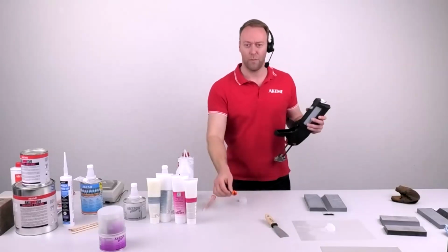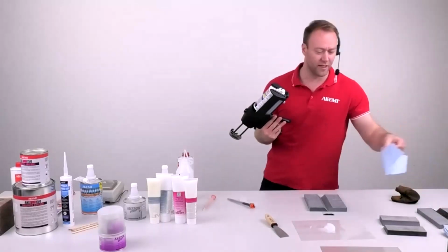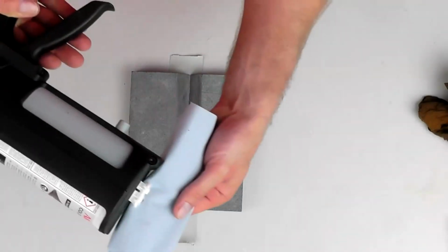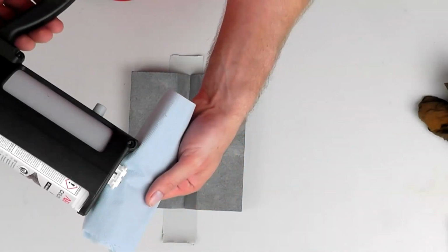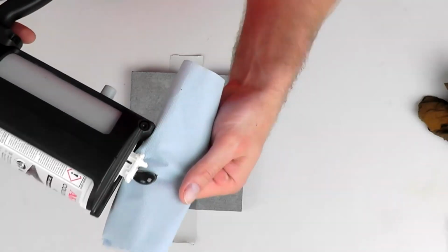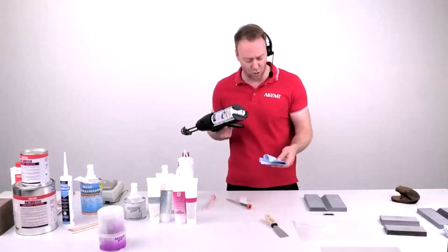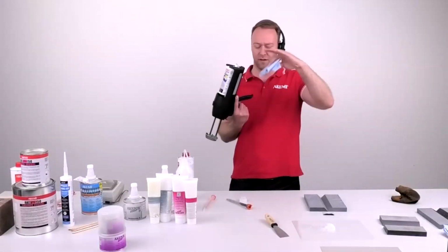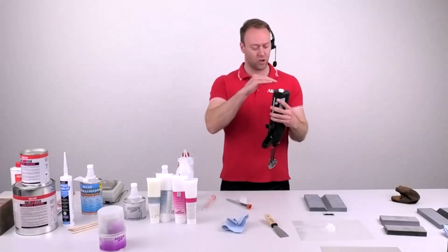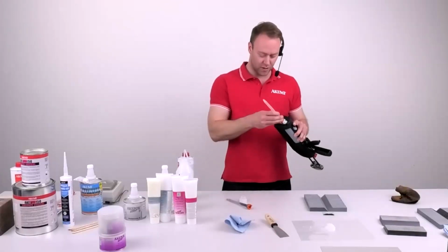Also here, with the mixing ratio you cannot make any mistakes, so you have to be sure that the mixing ratio comes out in a proper way. When you use a cartridge for the first time, press as long as both components come out of the chambers, because maybe during transport there will be a different filling status. So press them out so you're sure they come out at the same time. Place your mixing nozzles on top of it.